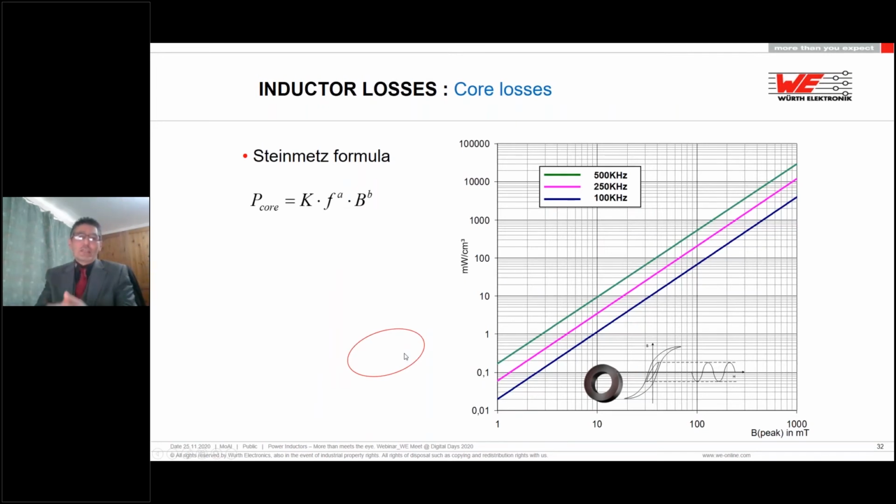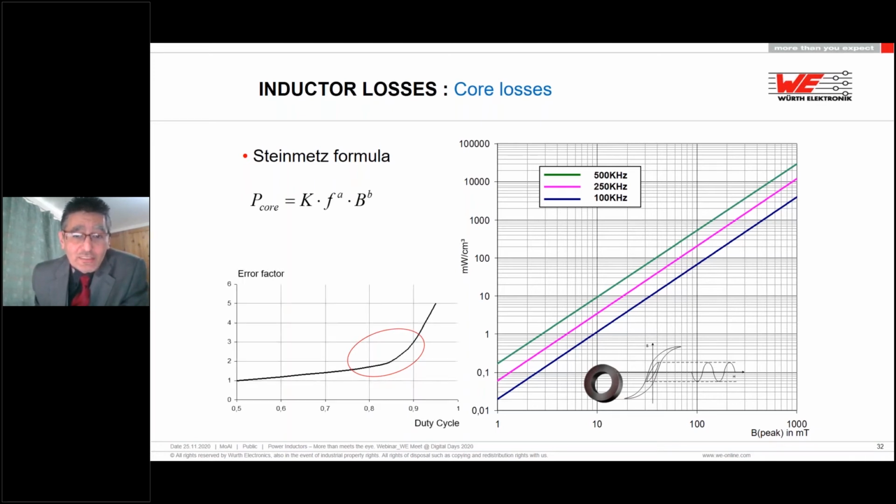So that's AC copper loss. You can see there's a lot more than I squared RDC. And if we look at the core loss, which is the other side of things, the core material that we use, I've used this myself in years gone by, designing inductors and transformers based on the curves that you see in here in order to calculate or roughly estimate core loss. We could never do anything about AC copper loss. We could calculate I squared RDC, and the next step was to estimate core loss, and this would guide us towards what we would be expecting in terms of losses in the transformer or the inductor.